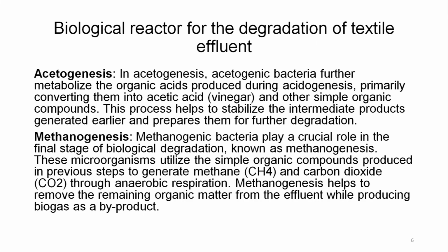So, by the intervention of acidogenesis and acetogenesis, different types of molecular fragmentation are happening. Volatile fatty acids were formed in acidogenesis, whereas the same compounds were then converted by acetogenic bacteria to acetic acid, which is nothing but vinegar.